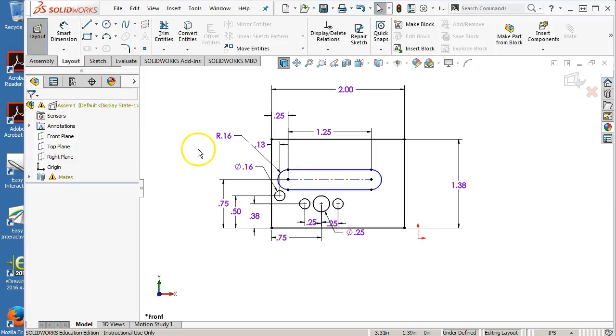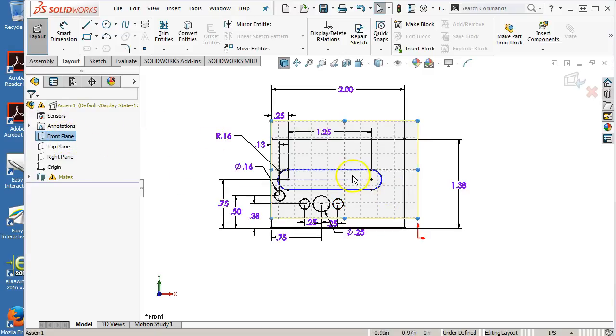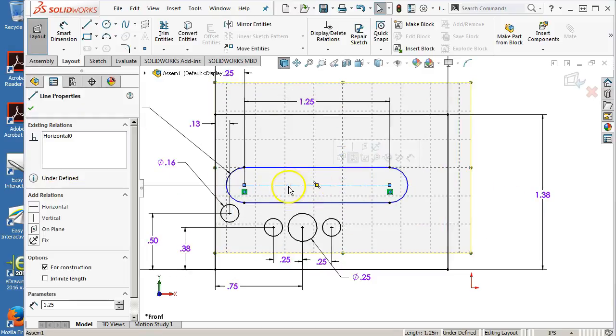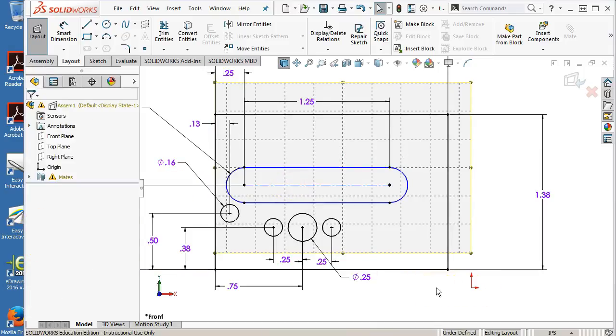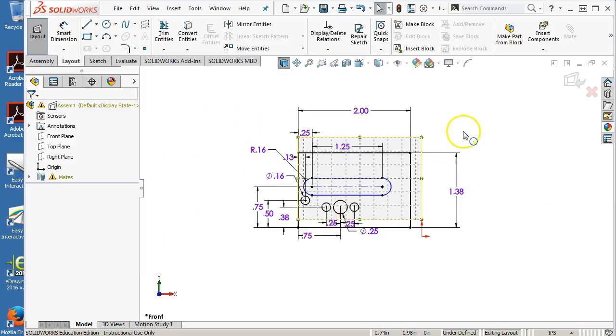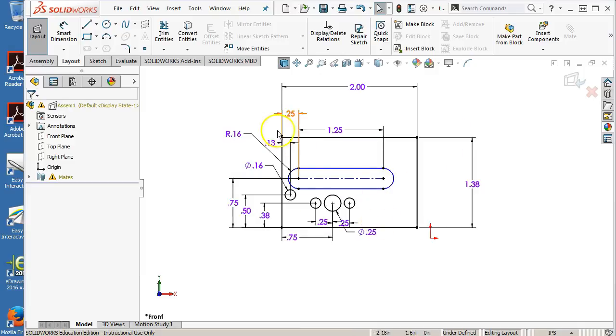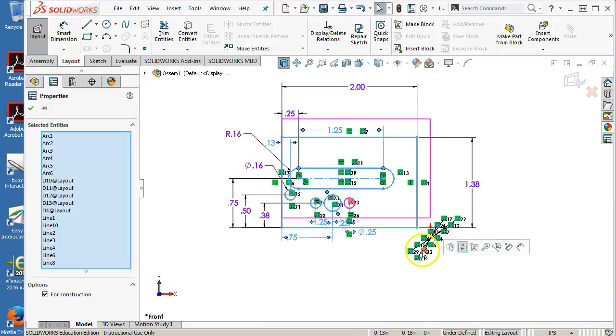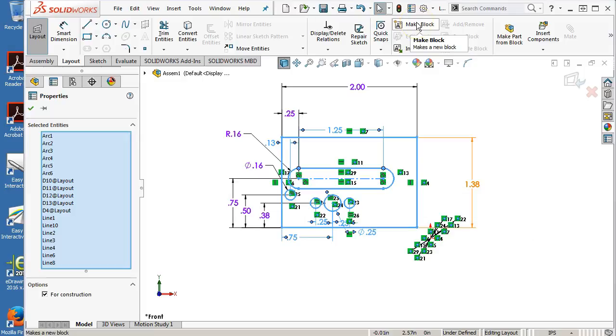Okay, so what it's telling me is that I need to go back into the front plane, grab that line, grab that center line, and make sure that it is on plane in the current selected plane. It is that picky. All right. If this is out of this plane or not shown as on plane, then it is existing in the 3D sketch where everything else was picked up on the front plane. All right, so let's try that again. Everything showed up that time.